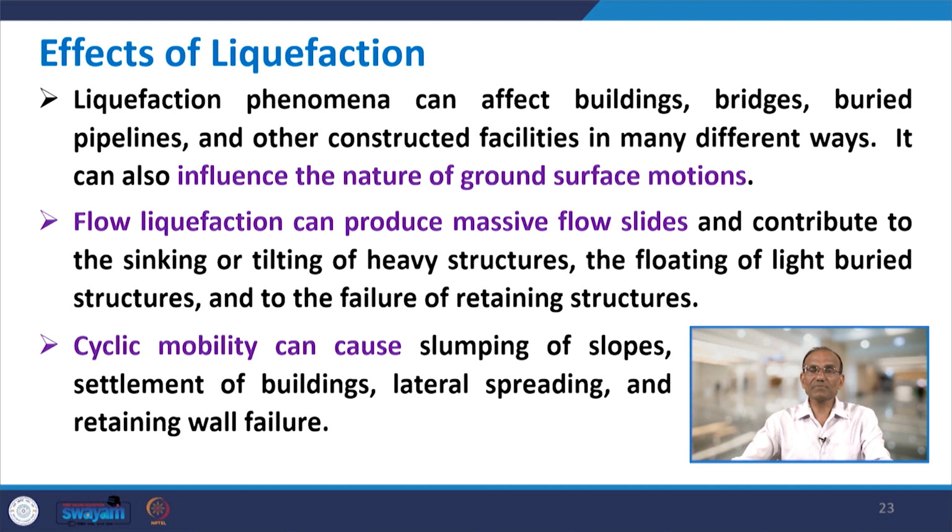Flow liquefaction can produce massive flow slides and contribute to the sinking or tilting of heavy structures, the floating of light buried structures and the failure of retaining structures. As far as cyclic mobility is concerned, it can cause slumping of slopes, settlement of buildings, lateral spreading and retaining wall failure. So, many effects are there, for flow liquefaction as well as for cyclic mobility.